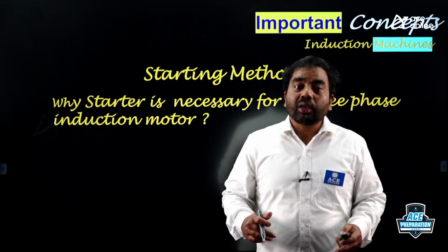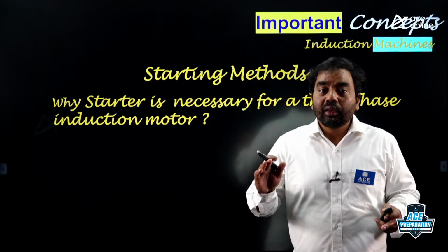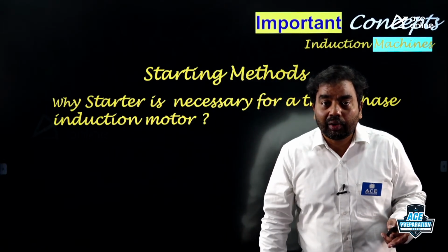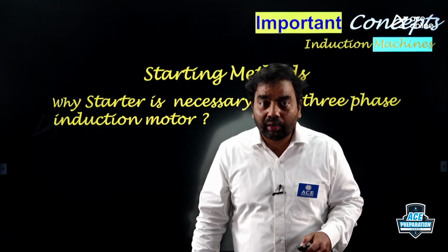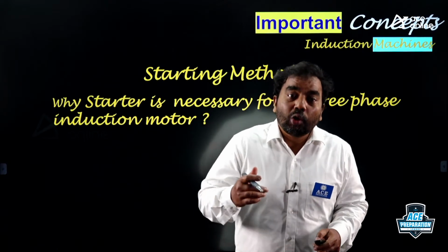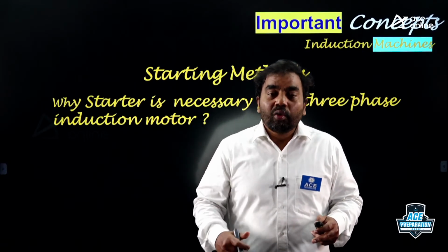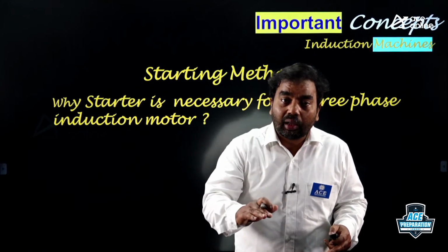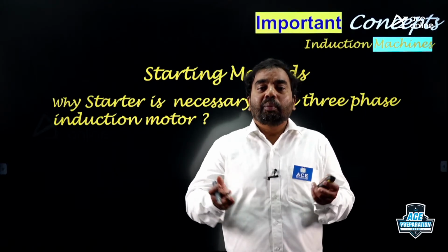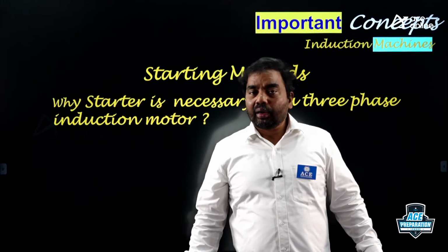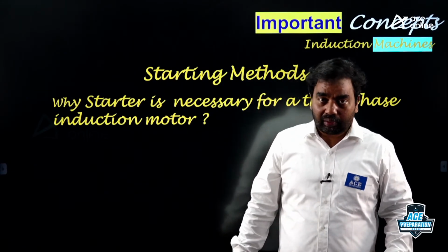But why not in running condition? In running condition, the relative speed will be less, flux cutting the rotor conductors will be less, EMF induced in the rotor conductors will be less, currents will be less, ohmic losses will be less, and temperatures will be less, windings will be safe. In other way, the load impedance is present in the rotor circuit during running. Why? Once the motor starts rotating, NR will increase, slip will decrease, R2 into (1/S minus 1) will build up, which increases the rotor impedance, and hence the currents will be less. So during running condition, we don't need any starters.